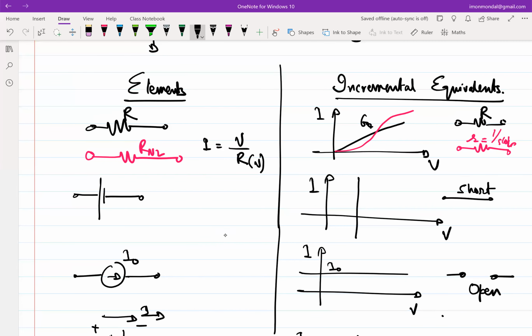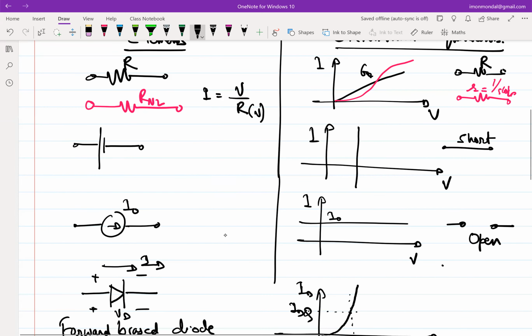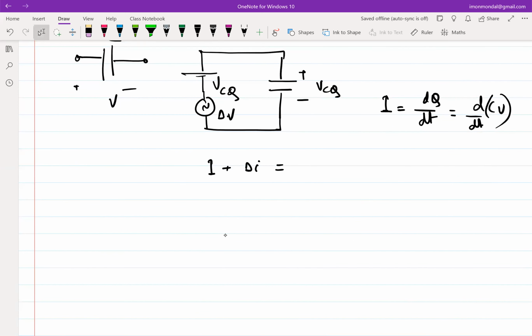So another way of stating a nonlinearity in the electrical domain is the fact that the component value changes when you apply currents through it or voltages across it, right? The component value can change maybe linearly. That can happen, but that change in component value makes the IV characteristics nonlinear, right? Is that clear, or should I spend more time on this? Okay. So the reason I was harping on this is,